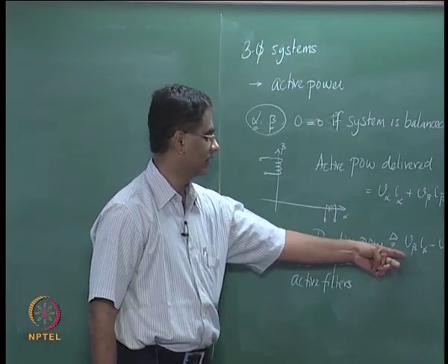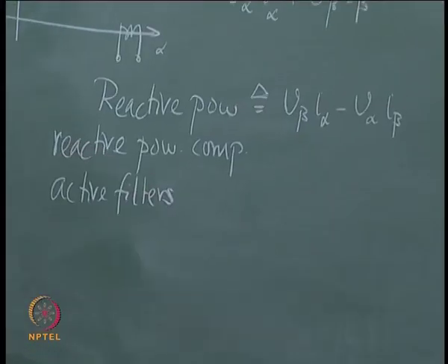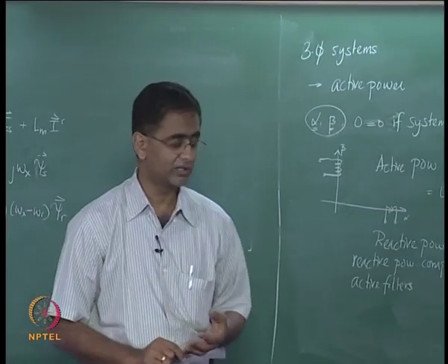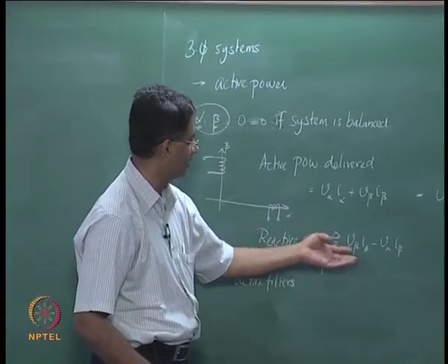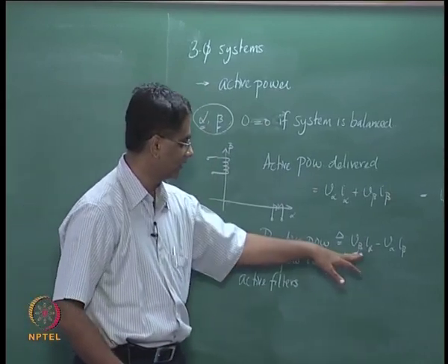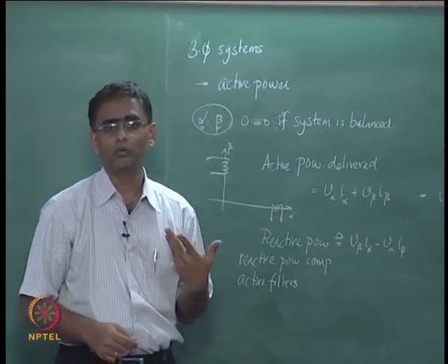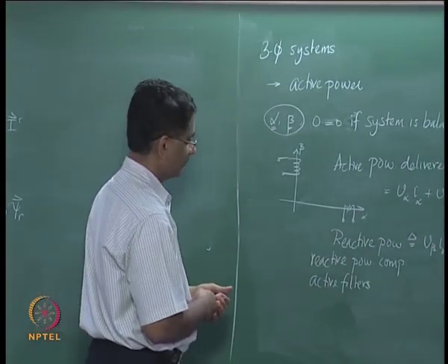One can of course try to substitute the inverse going from here to ABC and try to find out what is the resulting expression in terms of the ABC variables, but normally this computation is done after transforming ABC variables to the alpha beta reference, in which case these kind of expressions would be sufficient to determine the behavior of the 3-phase system.